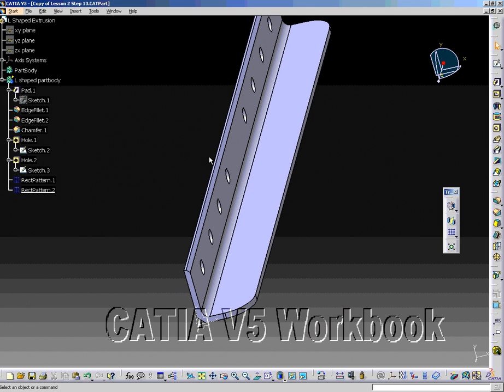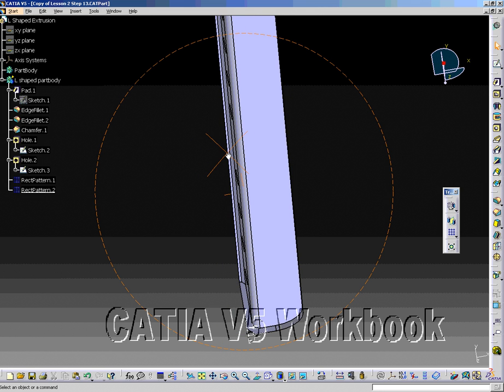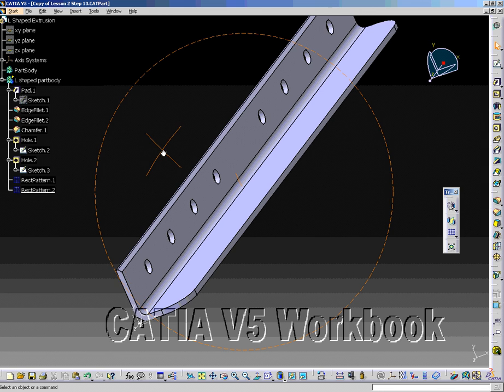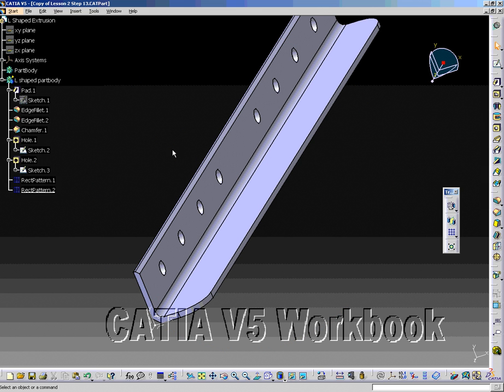The same rotation can be accomplished with the mouse only. Push the middle mouse button. Continue to hold the middle mouse button down and push down the left mouse button. The sequence of mouse buttons will bring up the same rotation sphere.